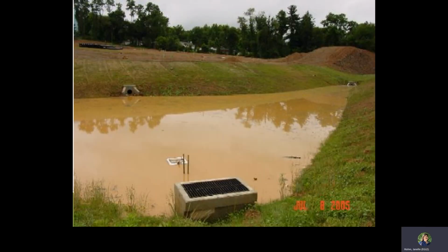Notice the suspended clays in the sediment basin. The stormwater runoff is still sediment laden as it exits the basin. A baffle could be added to the basin so that the stormwater runoff does not immediately flow out of the basin. There is a skimmer installed on the surface of this basin. Notice the white pipes. A skimmer is designed to remove the cleanest water from the surface of the basin. In this case, the water in the basin is still very sediment laden. In addition to adding baffles, PAMs are recommended if the soils on site contain clays or fine silts.